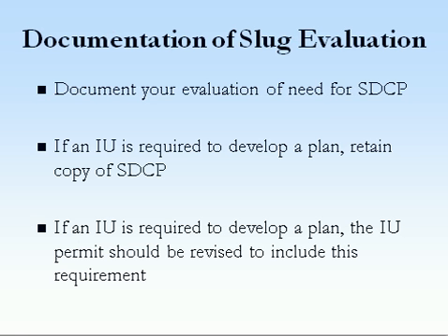So we've talked a little bit about the slug control plan, and once you've made that determination, that evaluation of whether or not the industry needs to have a slug discharge control plan, you need to document that. If you determine that they need to have one, then you need to keep a copy of it, and you also need to put in their permit that they are required to have a slug discharge control plan.